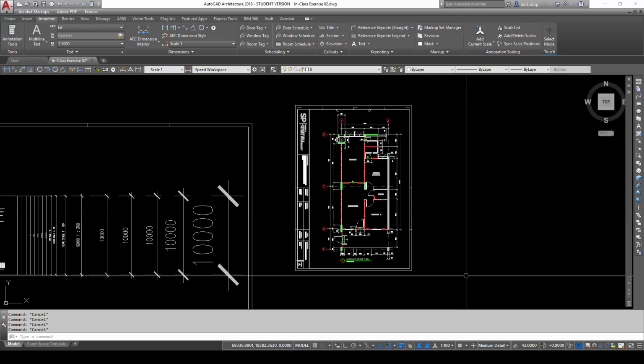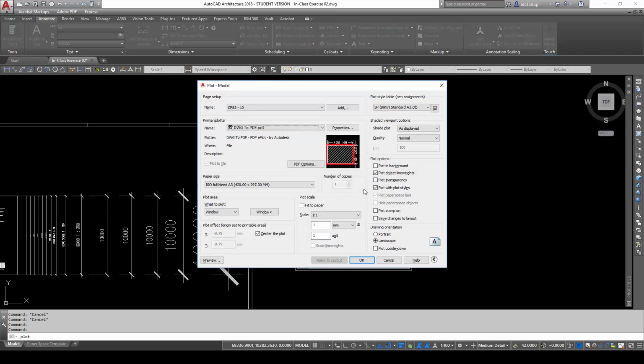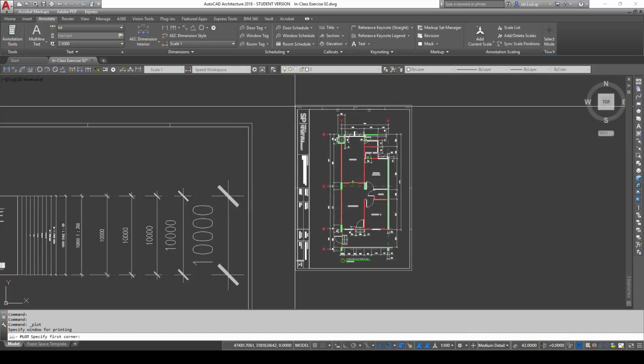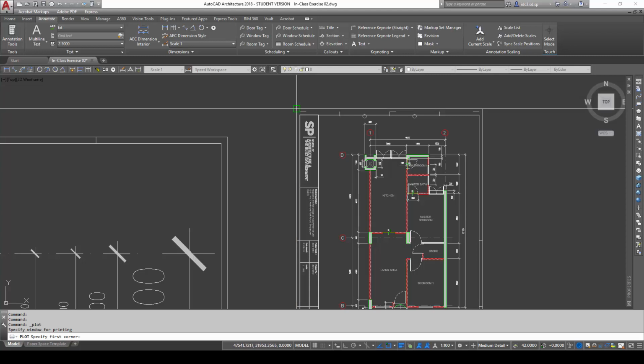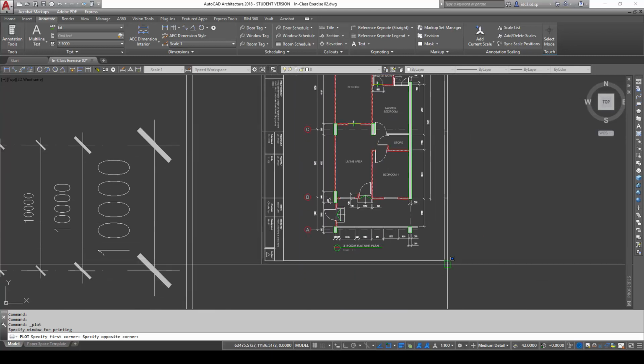with the drawing corrections and the amendments, we will go ahead and prepare the drawing for print with the print setup. Okay, we know that now this is an A3 size document to be printed at the scale of 1:50. All right, so I'm going to go ahead and click on Control P and look for A3 size. Okay, A3 size, and I'm going to window the entire drawing, entire boundary of the drawing here to here.